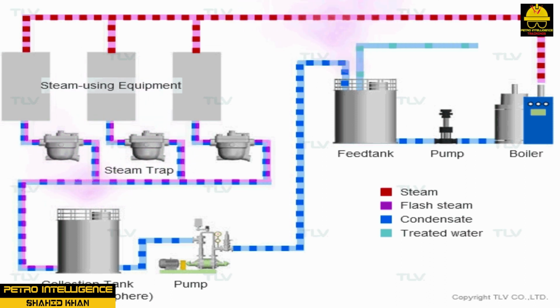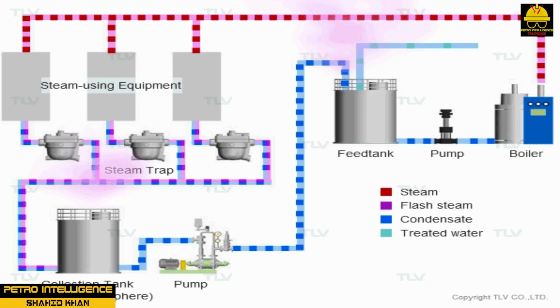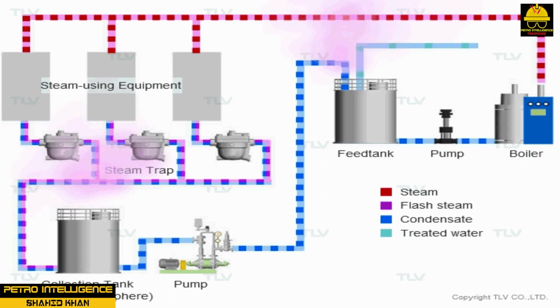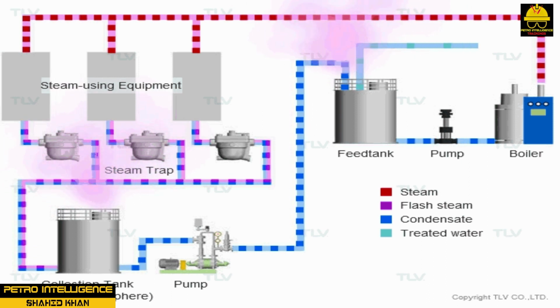Suspect condensate collected in a drum is closely monitored for hydrocarbon contamination. Depending upon the results of analysis, the condensate is pumped through a carbon filter and then routed to the deaerator.